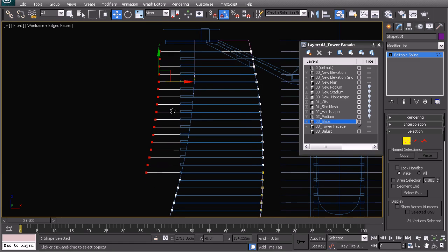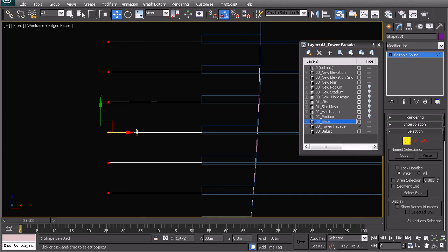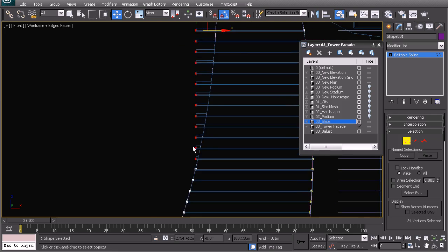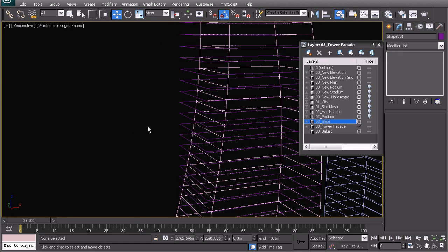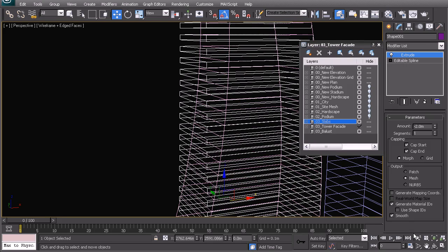So we pull all of them out, and then a little trick here, press R just to scale everything, and then just scale, making sure that this is in the middle, and just scale everything sideways until it all lines up. You can go a few times across your screen until you believe that you've basically straightened it out. You can then pull it back until you're happy with it being at the right point, until you hit this vertical line here. So basically we now have completed the slab edges, and these can immediately be extruded down just the way we did the other slabs on the podium.